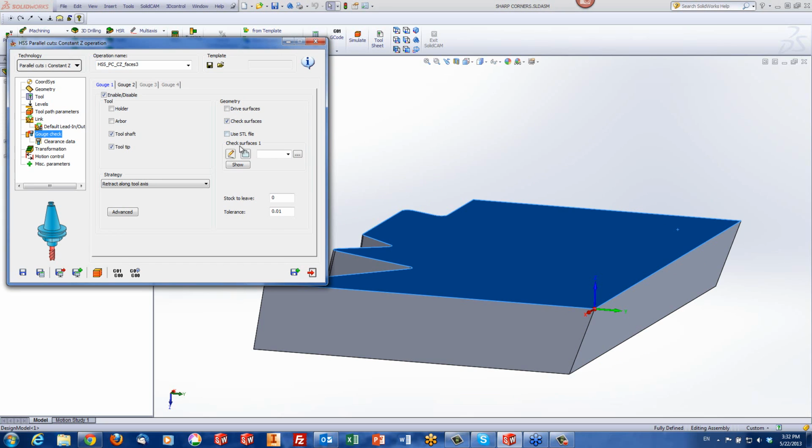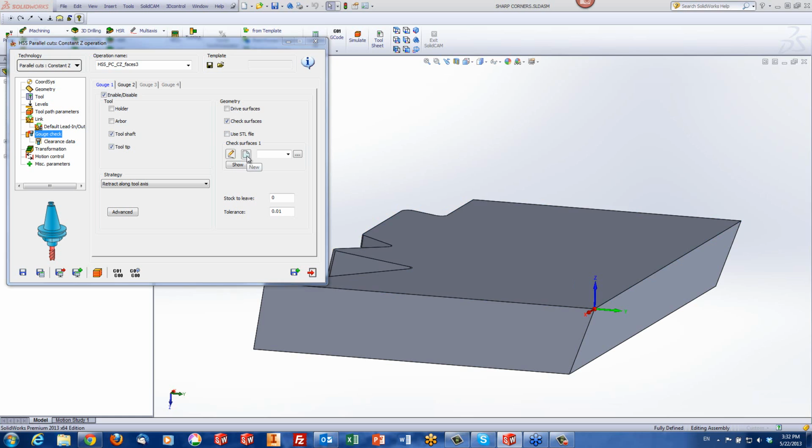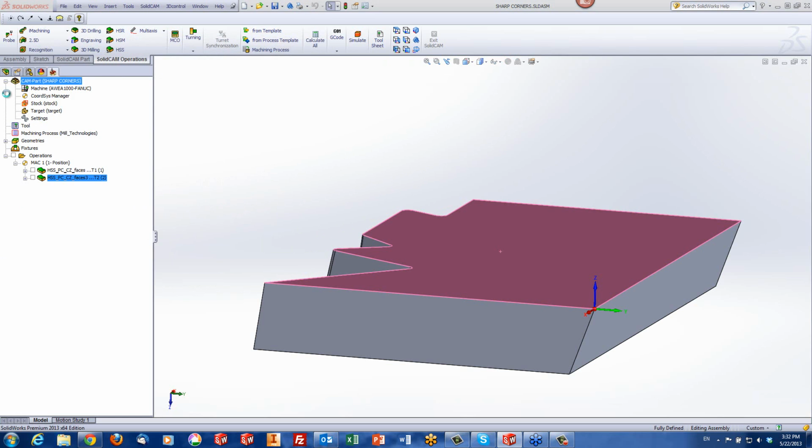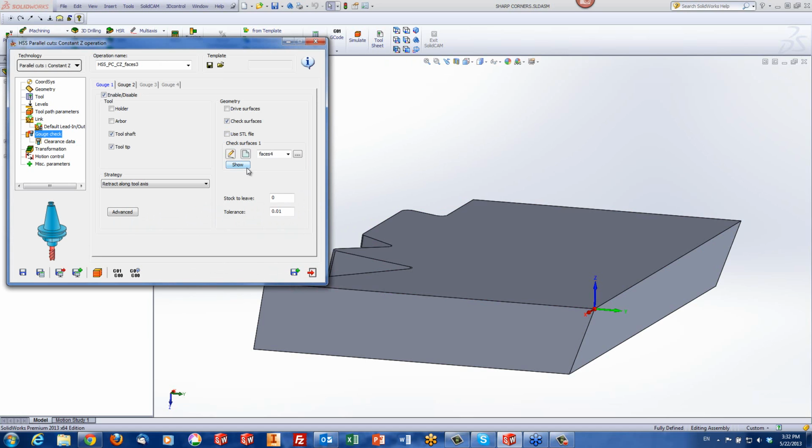We're talking about the check surfaces, so let's do one on the check surface over here. Now, what to do? Let's just leave out gouge points. In other words, just stop working. Don't look for any more points to machine on. Okay.